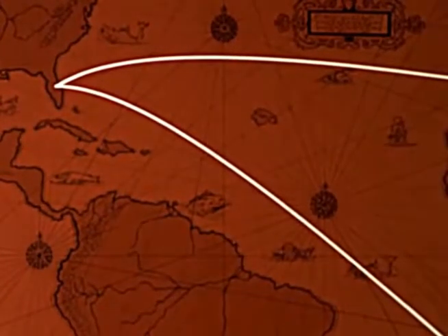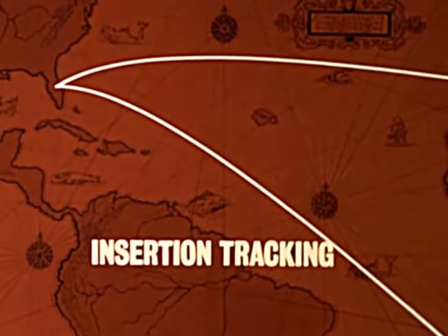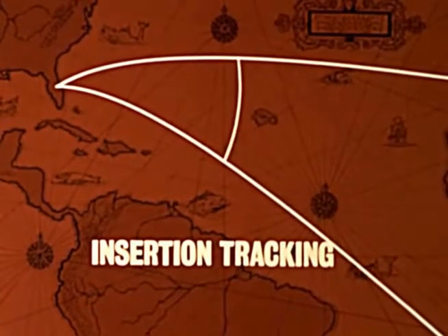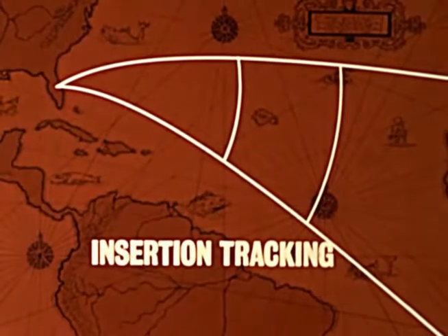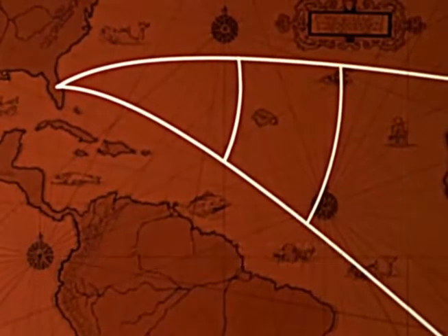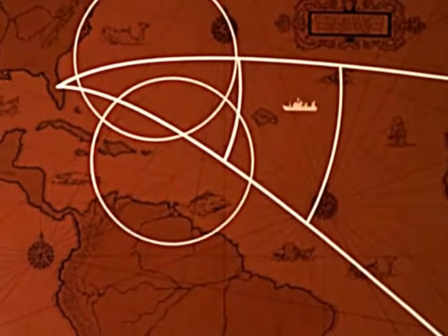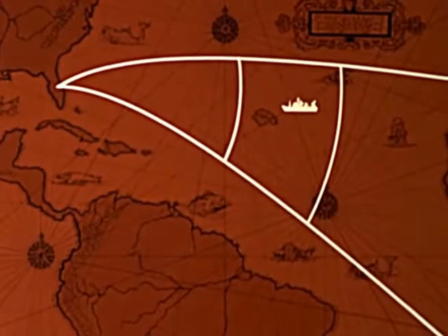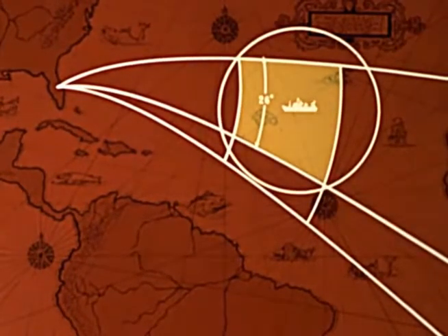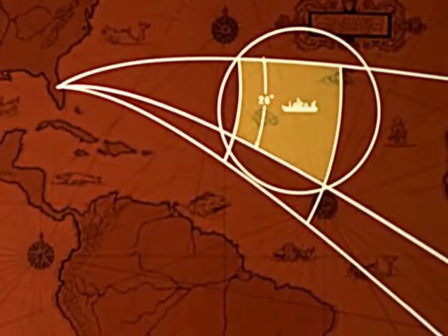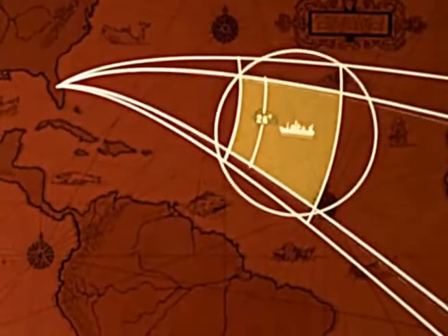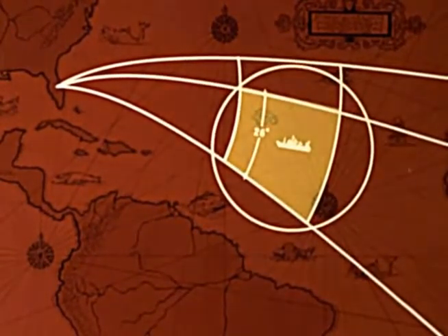There is an operational requirement to track the space vehicle during the complete launch phase and from orbit insertion to at least 3 minutes following insertion in order to verify that an acceptable orbit has been achieved. Some tracking coverage is obtained from stations on Bermuda and Antigua. However, since insertion can occur beyond these stations, the gap is filled by a tracking ship which can track over a launch azimuth range of 26 degrees. The choice of where this 26 degrees is located within the 72 degree and 108 degree limits is left to the mission planner.